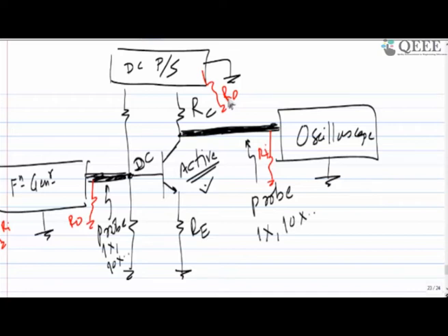How are they creating a problem? If you are doing this setup, whatever setup we just kept, it may create a problem because we were expecting the voltage over here, let's call it VB, to be equal to R2 by R1 plus R2 times VCC.